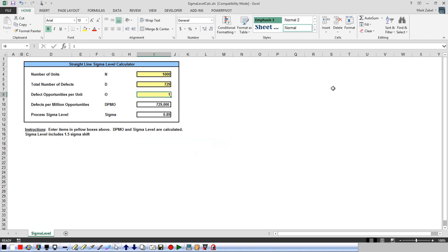And there's 40, each one there was 48 opportunities, right? Yep. So that tells me there's 15,188 defects per million opportunities. That's a sigma level of 3.67. That's it. Done. There's your sigma level if you want it, okay?